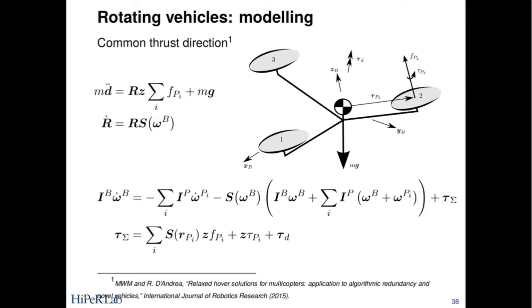So Newton tells us if there are no forces, there is no acceleration. In rotation, that's not true. And it's not true because of the complexity of the mass moment of inertia matrix, loosely speaking. But we can use this idea now to try and control an aerial vehicle when we lose an actuator. So we can use this sort of nonlinearity to try and control the vehicle.